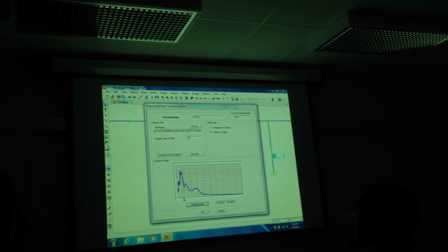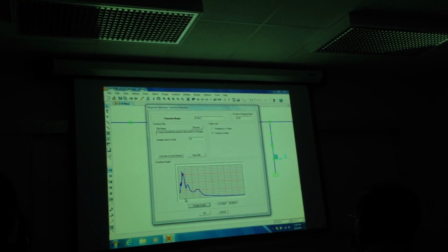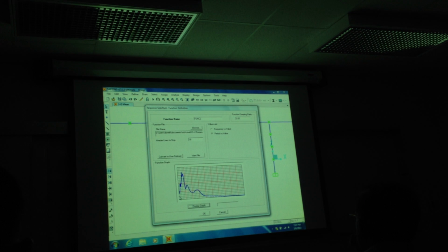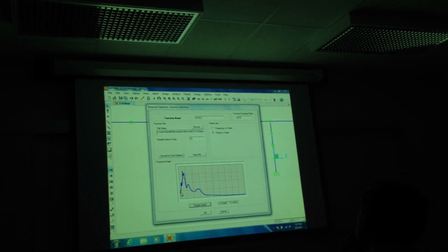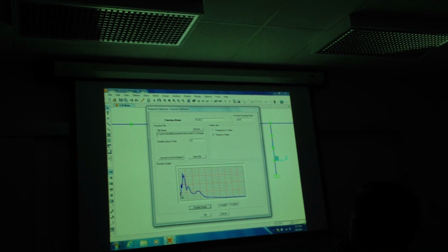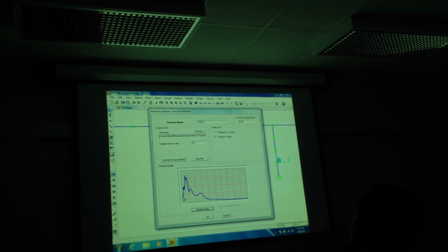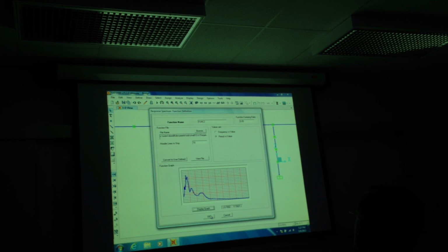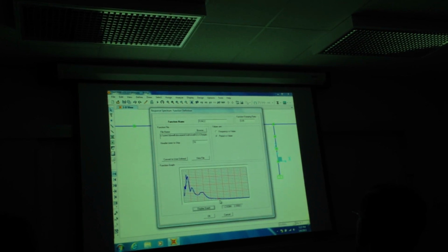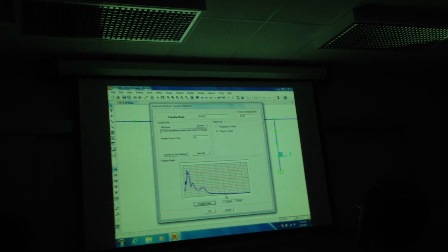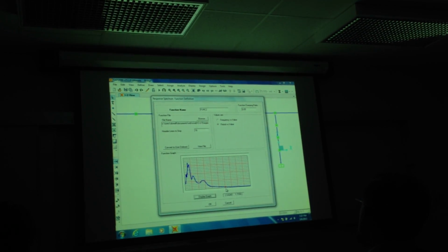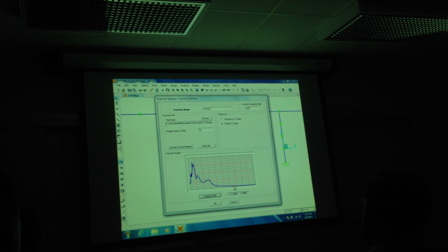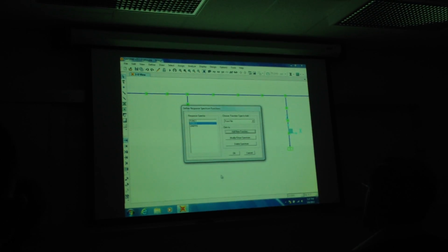If I look at a period here of about 0.35 seconds, we're up at above 1 g, 45 point something feet per second squared, so there's amplification. Peak ground acceleration over on the left here is at about 11, so that's about 1/3 g. Okay. If we have a very flexible structure, let's say you have a 3-second period way out here, it's only 1.7 feet per second squared, so it's very, very small. So again, go back to that base isolation idea. Okay, so that's function 2.